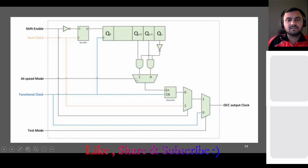So once your at-speed mode is 1, this mode will be selected, and then your functional clock will come, and based on that scan enable, this will generate the output. Suppose your test mode is 0, that means this functional clock will be bypassed. That means you are in the functional mode, you are not in the test mode. But once your test mode is 1, you are in the test mode, like you are in the shifting mode. Then it will check for this scan enable. If your scan enable is 1, that means your scan clock will be bypassed here. That means you are shifting your data, like you are just loading your data to the flops.